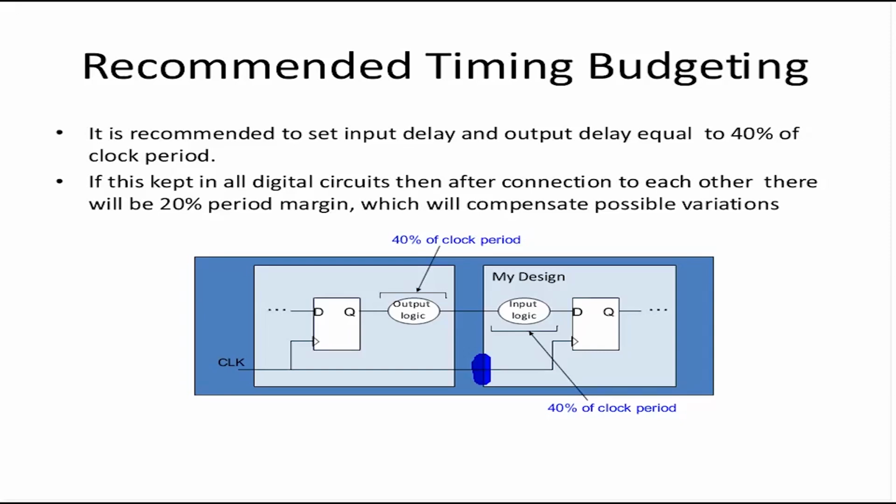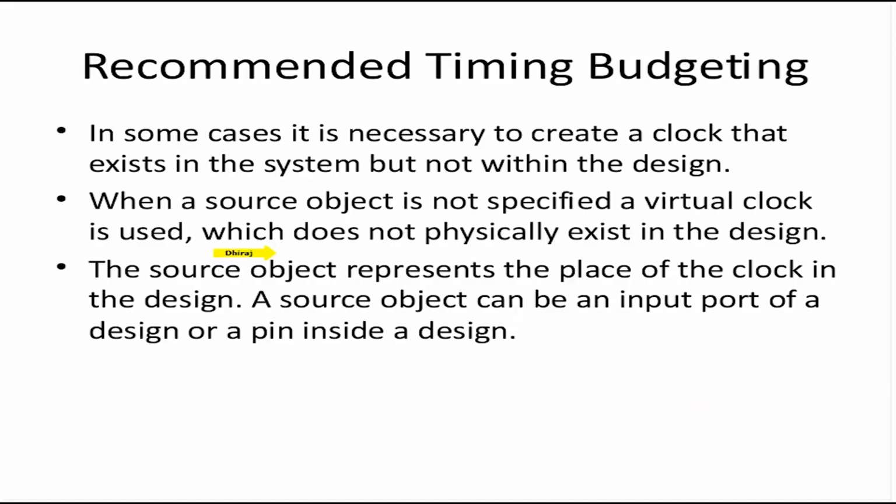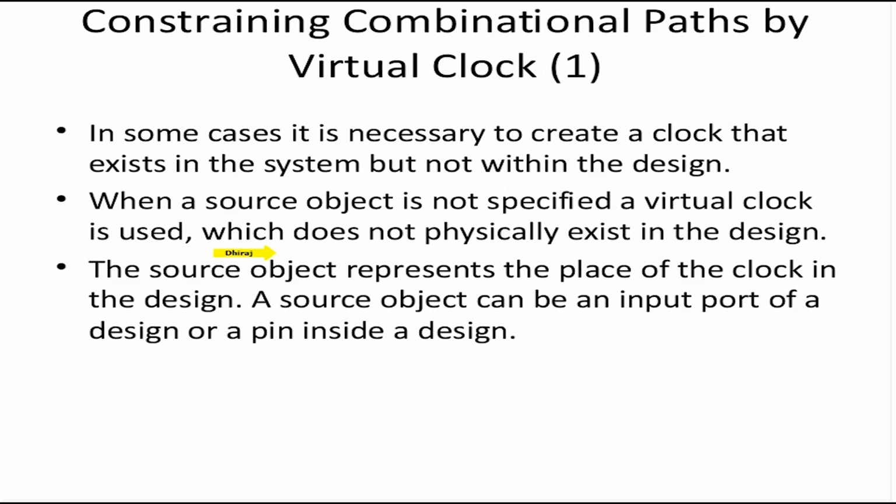In the external world, there is some other clock that drives this input. It's not the same clock, and this external clock, whatever clock is used externally, is nowhere used in your design. The only use it has is that it launches the input data. So this is the case where this external clock is not part of our design, but it's part of the system in which our design will sit. This is what is said here: sometimes it is necessary to create a clock that exists in the system but not in the design.